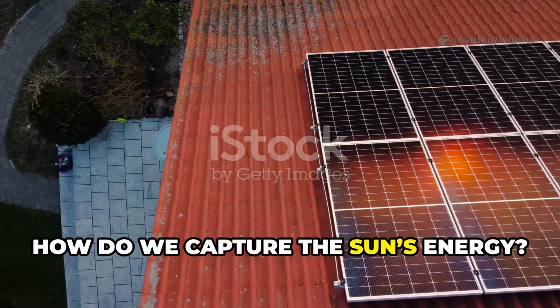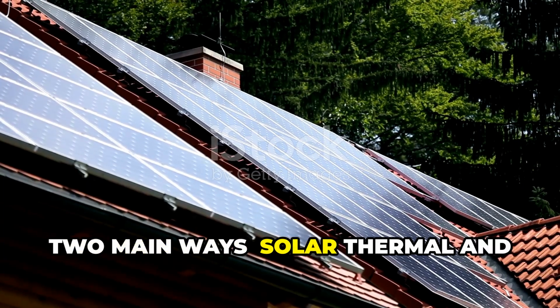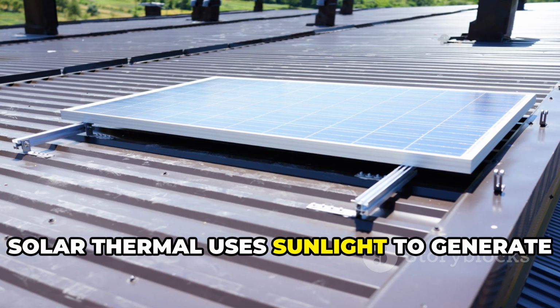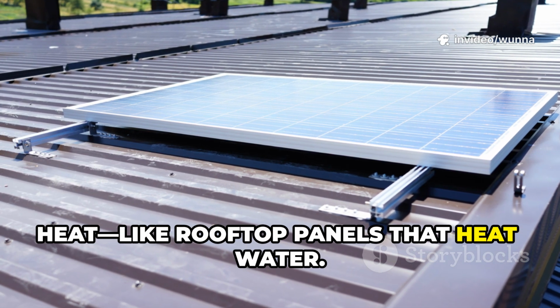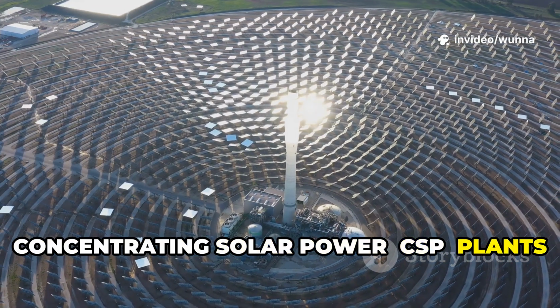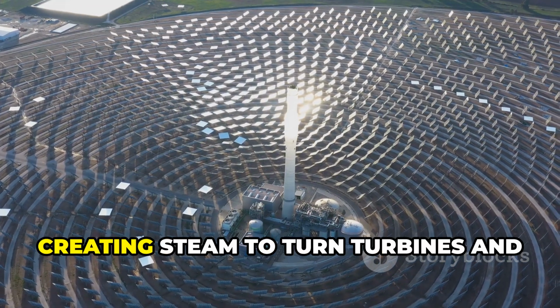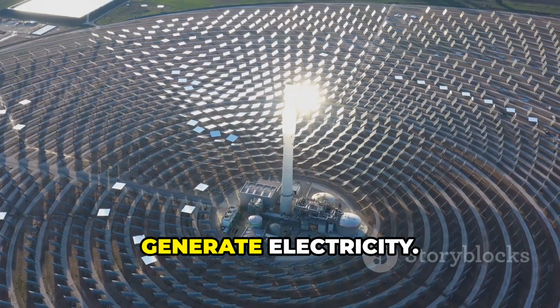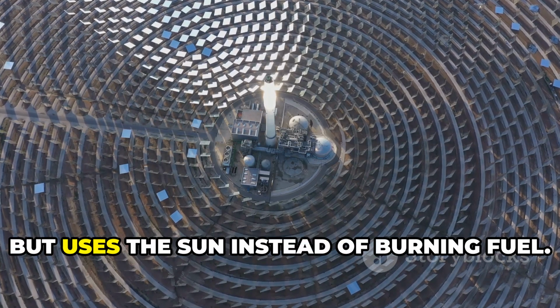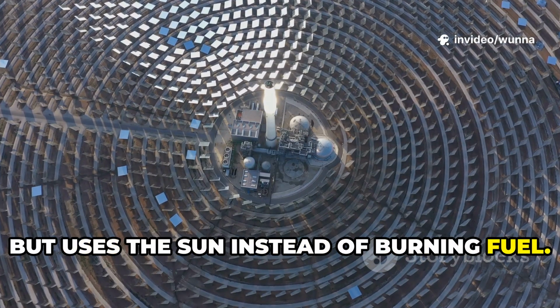How do we capture the sun's energy? Two main ways: solar thermal and photovoltaics, PV. Solar thermal uses sunlight to generate heat, like rooftop panels that heat water. On a larger scale, concentrating solar power, CSP plants use mirrors to focus sunlight, creating steam to turn turbines and generate electricity. CSP is similar to coal or nuclear plants, but uses the sun instead of burning fuel.